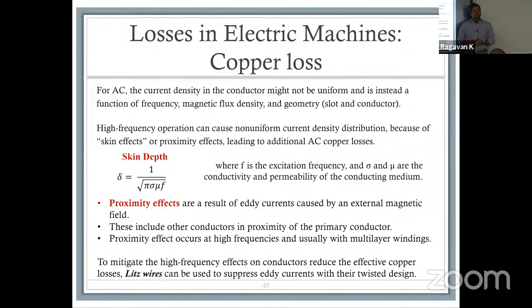Why is that a problem? It's a problem because we designed the conductor to carry the entire current. If I end up getting into a system where 60% of my conductor never sees the current, then I squared R means my I in that small region is very high, which means I squared R is going to be substantially higher. So my heating in my conductor will be a lot. As a result, what do we do?